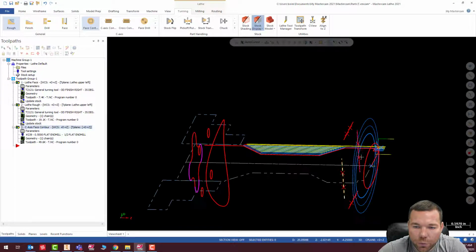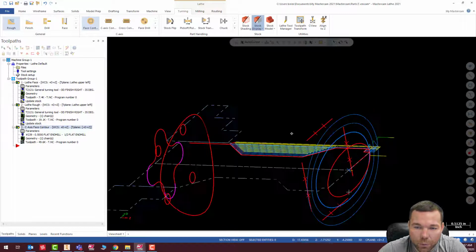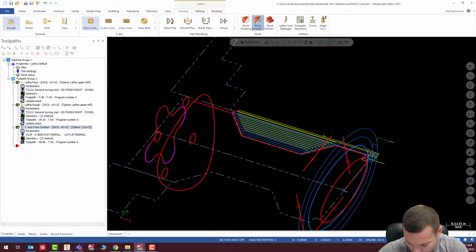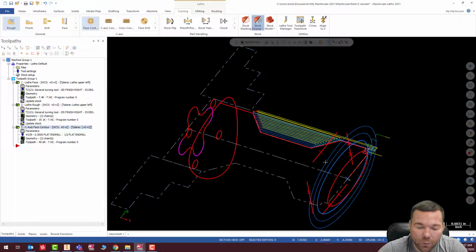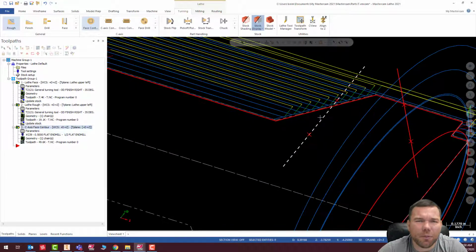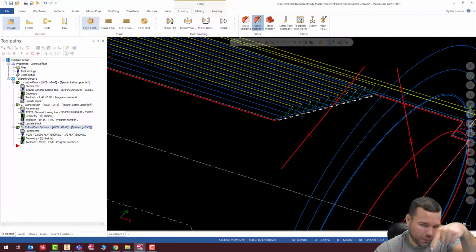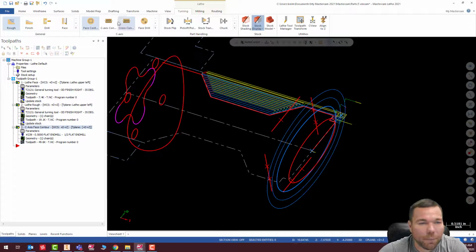Next thing we're going to do is we're going to put these flats on here before we drill it, because we really can't drill it until after we put the flats on. I guess we could, but it wouldn't be smart. You'd want to drill into a flat rather than the side of a round surface. Makes it a little more difficult if you try and do that.